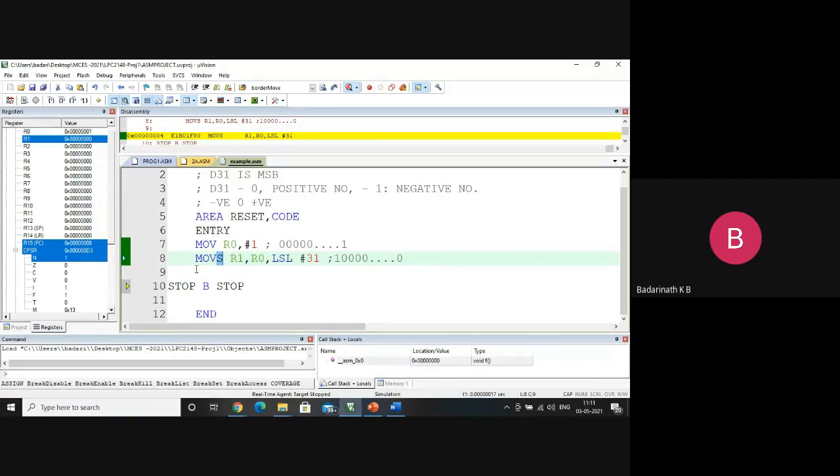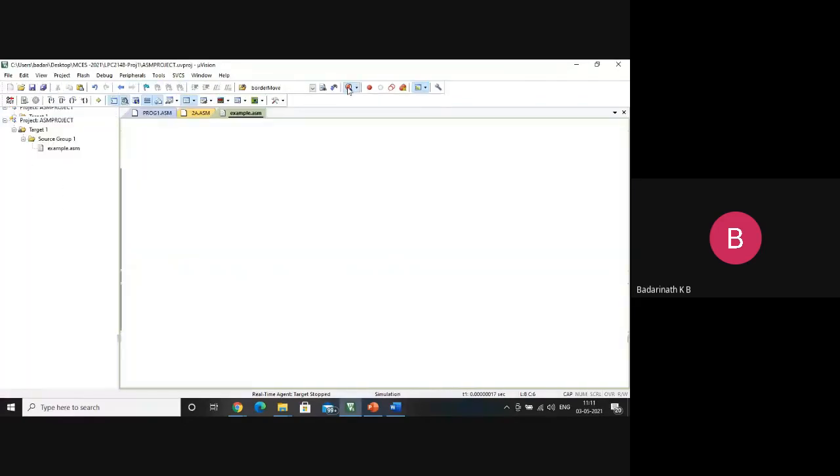If I want to implement logic, like if the number is less than something, what I can do is look at this flag and write a jump instruction. So the branch instructions, by looking at the flags, give a programmer the facility to implement if and else logic based on less than, greater than, equal, and all those. So now we have seen in this discussion how the sign flag works, and how the zero flag works. Similarly, how does the carry flag work? Last 2 minutes, please bear with me now.